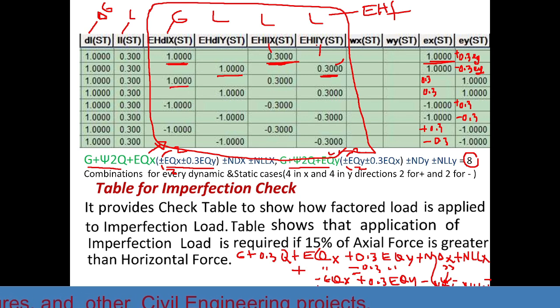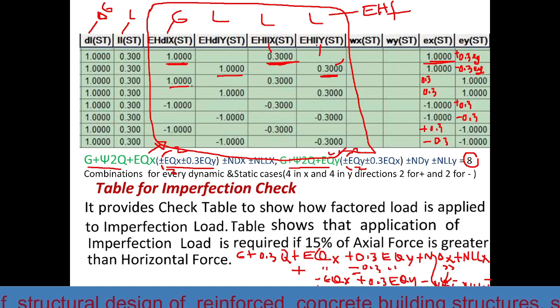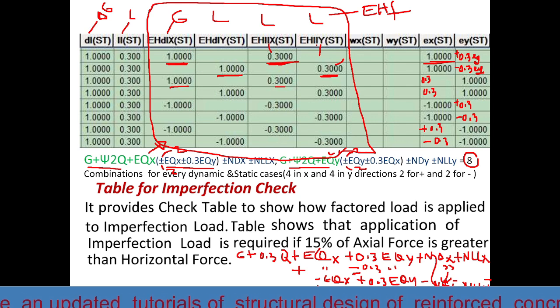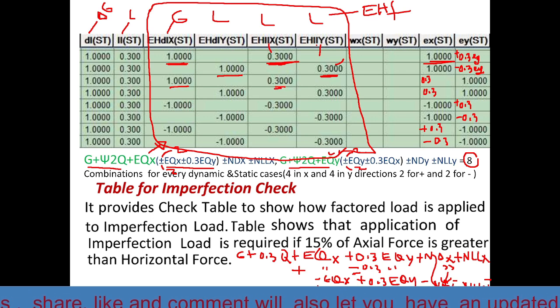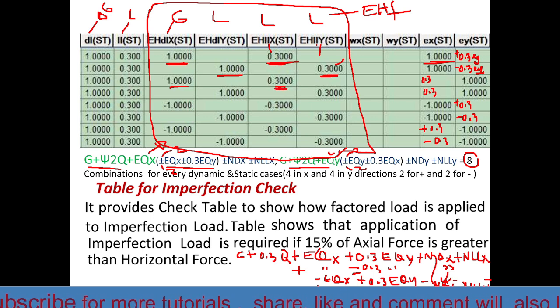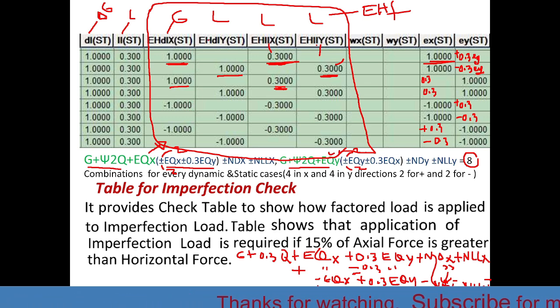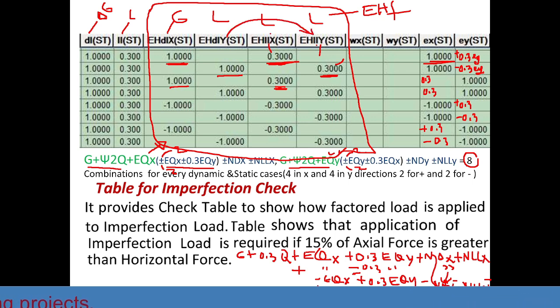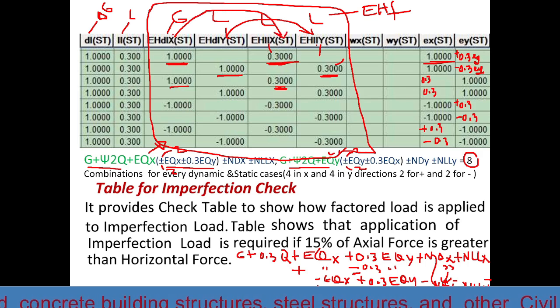And also here, in a similar way, the notional load due to the dead load in x positive direction should be combined with the notional load due to the live load in x positive direction. This one. So y direction must be combined with y direction, and x direction must be combined with x direction.